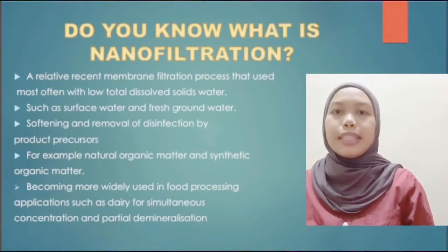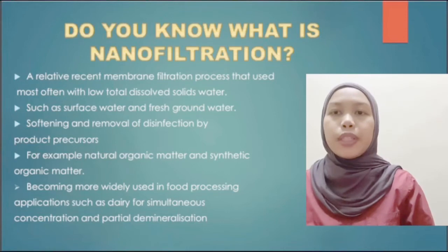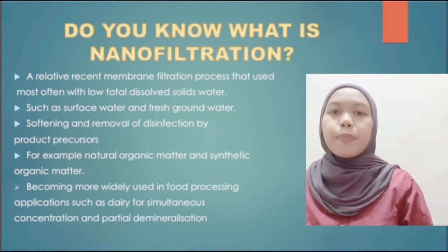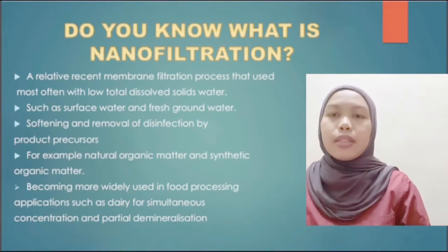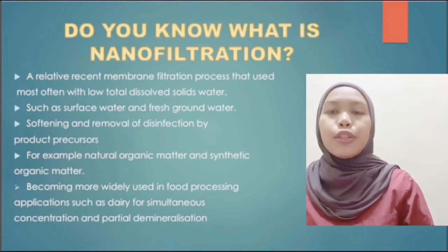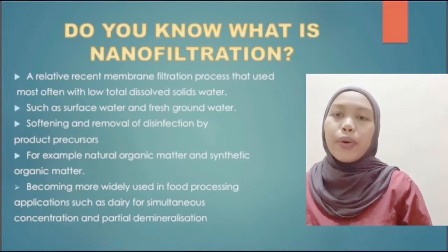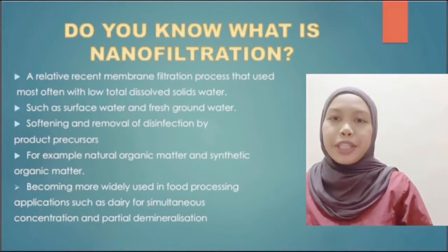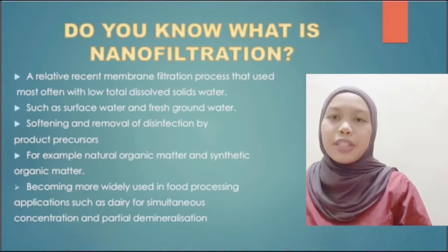Nanofiltration is a relatively recent membrane filtration process that is used most often with low total dissolved solid water, such as surface water and fresh groundwater. Its purpose is softening and removal of disinfection by-product precursors, for example, natural organic matter and synthetic organic matter. It has become more widely used in food processing applications such as dairy for simultaneous concentration and partial demineralization.